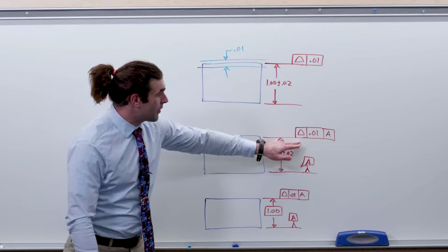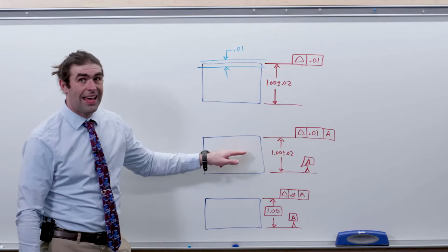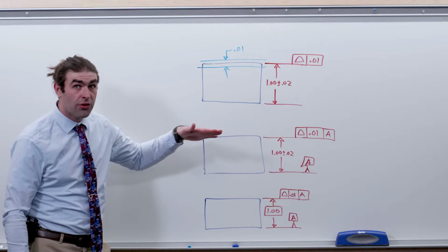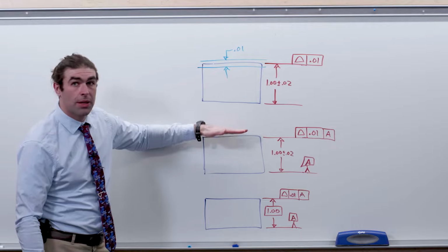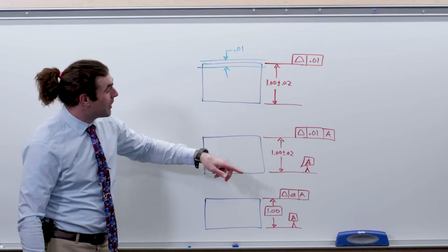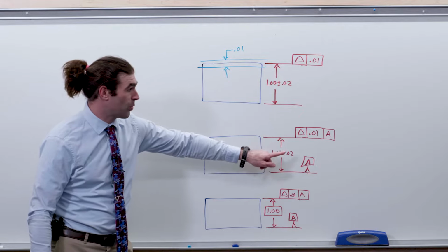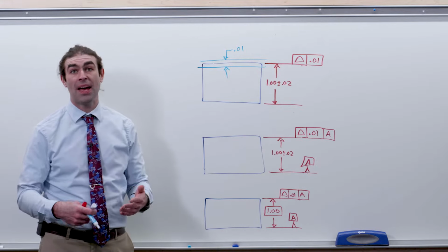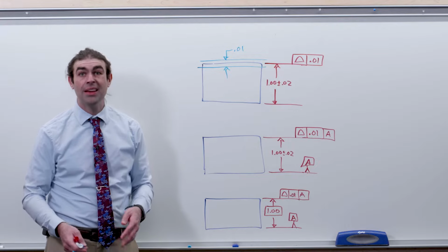So what this does, we've got a 10 thousandths tolerance zone to A. So that's essentially a parallelism callout. That tolerance zone needs to be parallel to A, but it's located with this larger plus or minus dimension. So this is essentially profile masquerading as a parallelism tolerance.